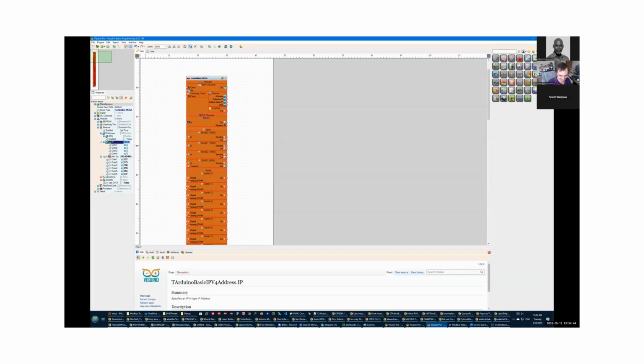Okay, so let's see, 192.168.0.201. So a different IP, and I need to enable it. Okay. So we did this. Anything else? Yeah, no, the other protocol is disabled, and we need Modbus, and it will be client serial.